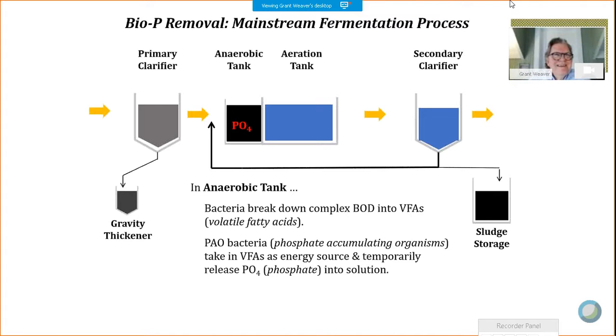Crazy as it seems, this is definitely one of those counterintuitive things. The first step in phosphorus removal is to put more phosphorus in the solution. And that happens when the bacteria either break down and die and they release phosphorus, which is not a good thing. That's a more problematic source of phosphorus.